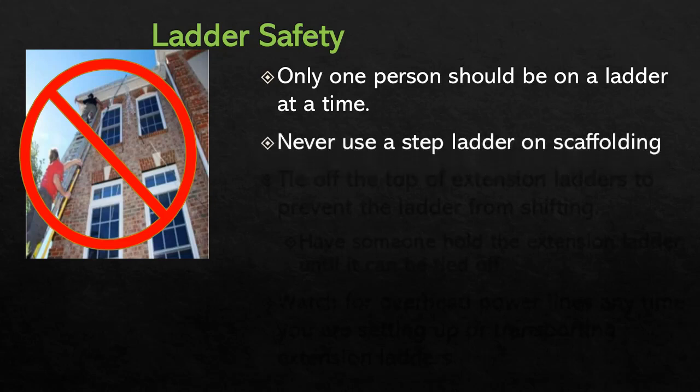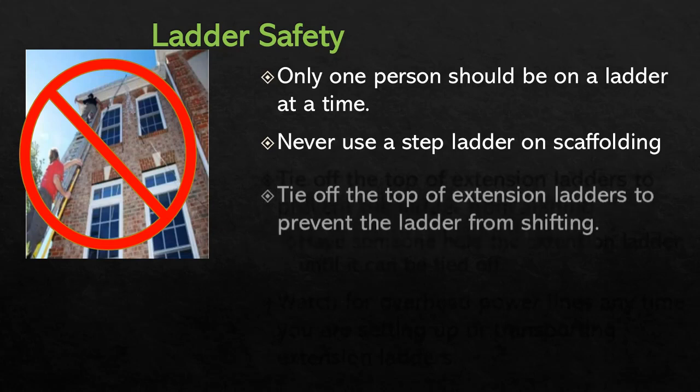Never, ever use a stepladder on scaffolding. That's a combination of too many inherently unstable things together. There are much easier ways to get greater elevation, like build an extra couple of bucks on your scaffolding. But using a stepladder on scaffolding is an inherently dangerous activity.